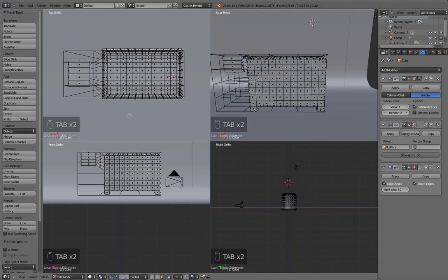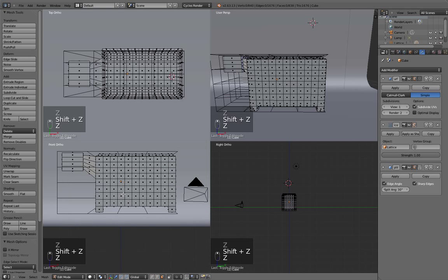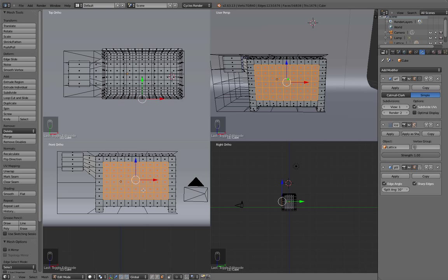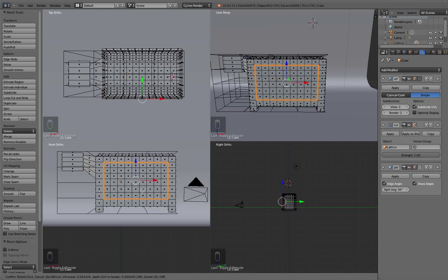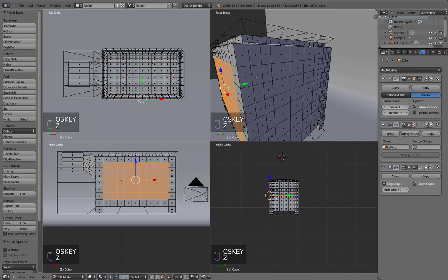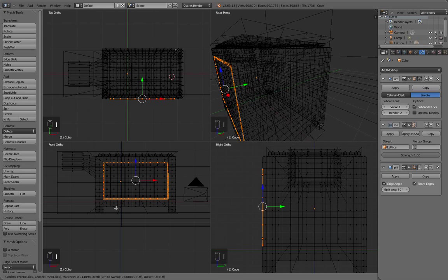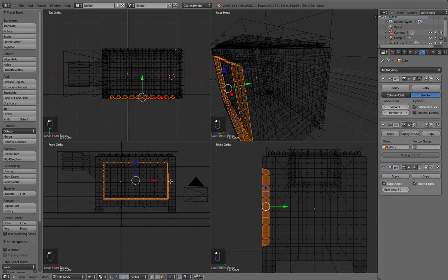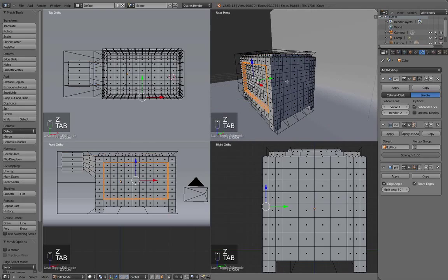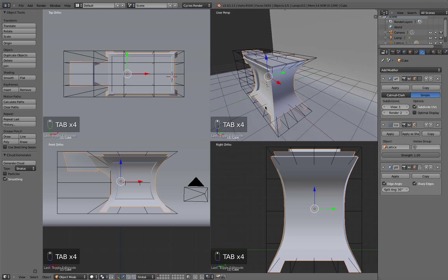So I'm just going to select, and I'm going to do this in flat mode. I'm going to press B for a border select, and select the middle faces here, and then again press I to make an inset. Then I'm going to hold down Control on the keyboard to inset it inwards. I'm going to undo that, I did that wrong. I'm going to do this in wireframe mode, and again I to inset it by maybe that much, and then Control to bring it in, and that just gives us some dynamic to what we're making here.